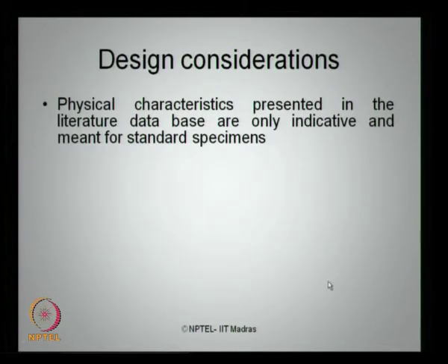In addition, physical characteristics present in the literature are very important to understand, but they are only indicative. For example, if the material has a yield value of let us say 250 megapascal, it is only an indicative value which is for a standard specimen, but in reality, depending upon the material you are trying to use, the structural loading in the actual environment may vary these kinds of properties.